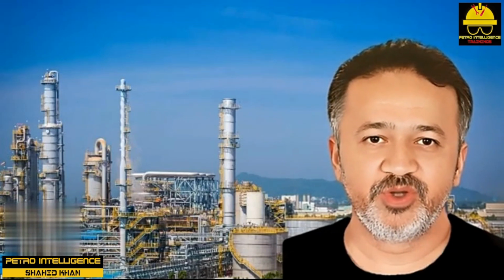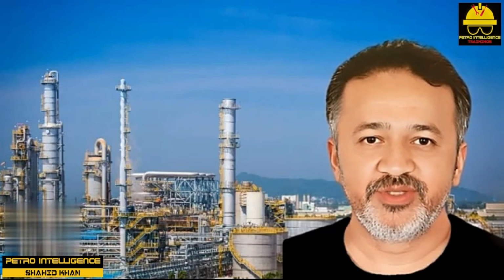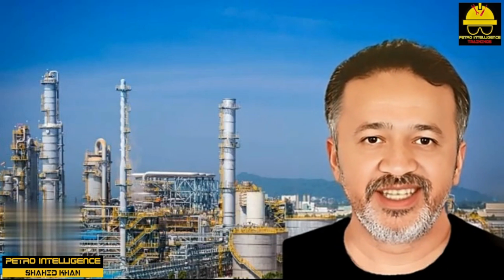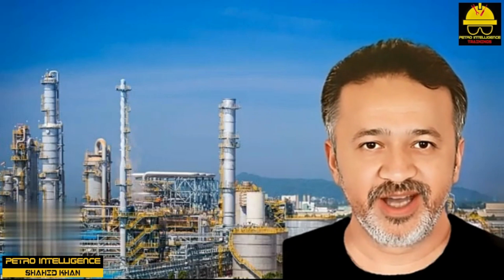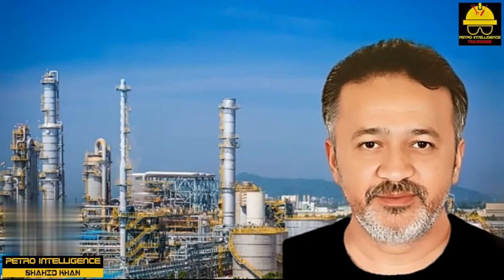If the pressure drop per tray is less than the height of the weir, then poor fractionation is due to weeping or dumping. One way to stop trays from leaking or weeping is to increase the reflux rate. If the reboiler is on automatic temperature control, increasing the reflux flow must result in increased reboiler duty. This will increase the vapor flow through the trays and the dry tray pressure drop. The higher dry tray pressure drop may then stop tray deck leakage. The net effect is that the higher reflux rate restores the tray efficiency.